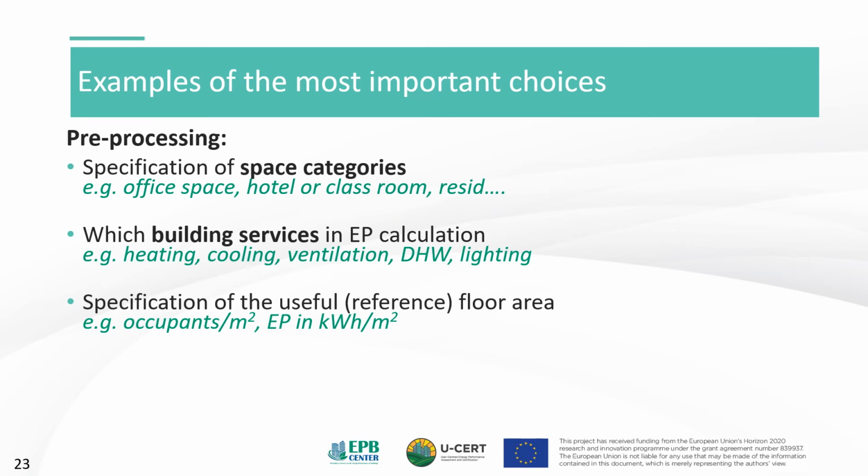Specification of the useful or reference floor area, which is important for instance, when you speak about the number of occupants per square meter. It's very important that you speak about the same useful floor area definition and specification. And of course, which is self-evident, if the energy performance is expressed per square meter, kilowatt hours per square meter, it's very important that you use the same definition of the square meters.